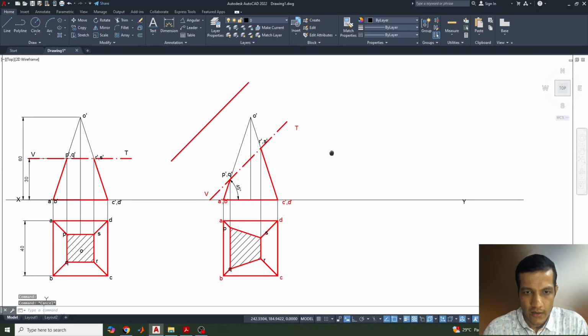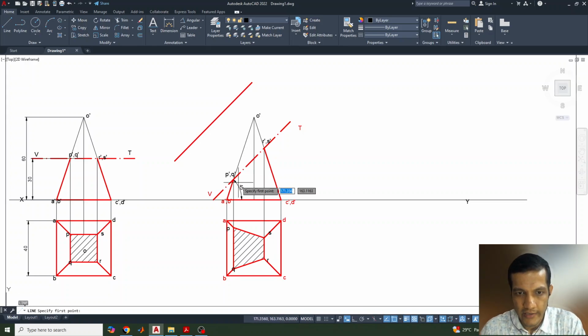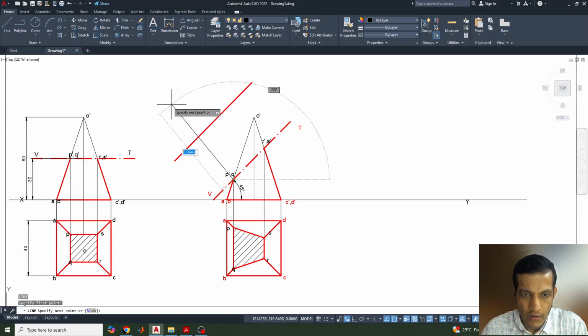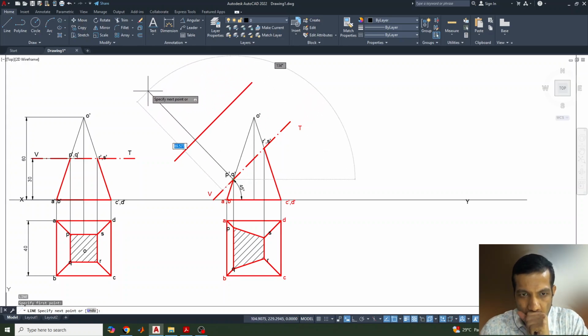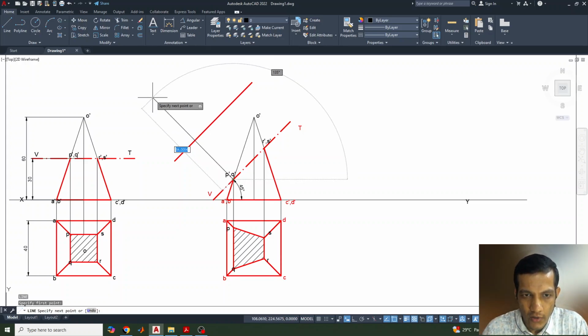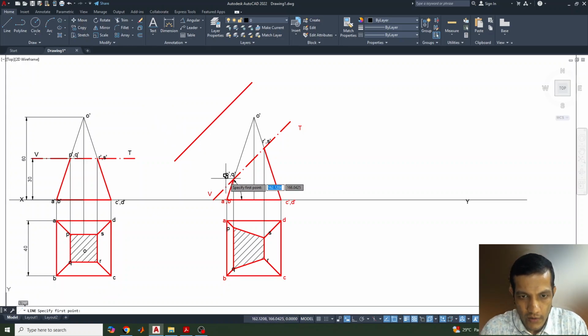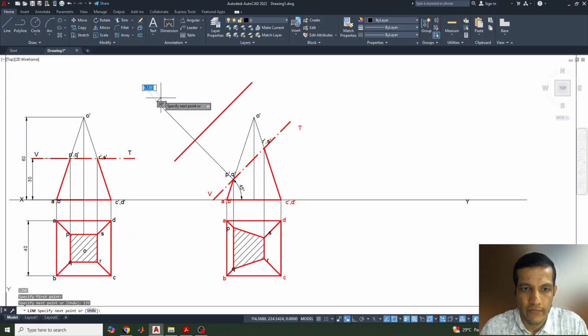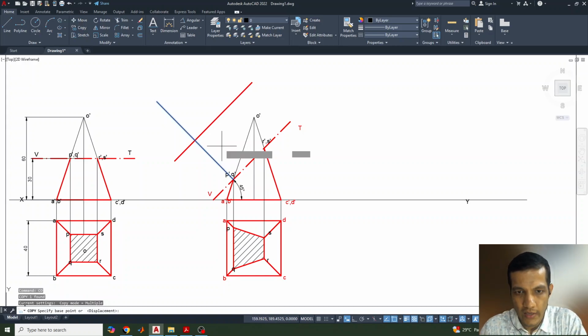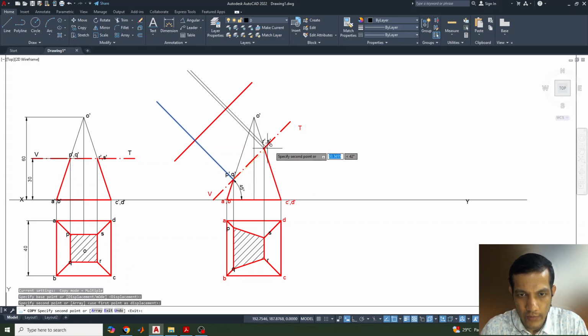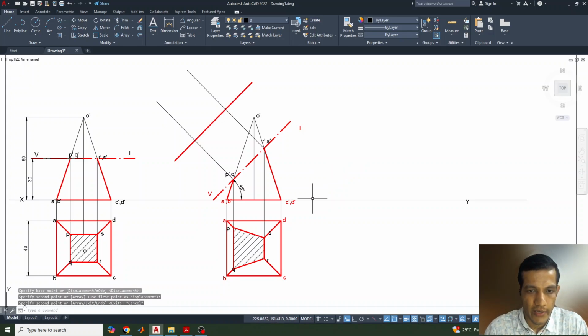Okay, yeah. The next thing is we need to draw the vertical lines from here. Yeah, in this way. So I'll take a height of let's suppose 80 and sorry, Control Z, L enter, select this point and 80 tab 135. Okay, like that we need to draw. And same thing, I can select this, I can copy, enter, from this base point to next base point I can keep it. Okay, my job is done mostly. The next thing is what I need to do, this projected view I need to keep it here.